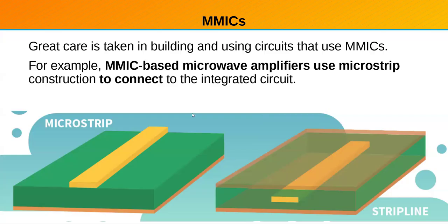And you kind of want to do that to control the impedance and also the length of them so that you don't get phase differences. Like if you're doing I and Q circuits where they have to be 90 degrees out of phase, you want to make sure that you don't get a phase shift between the two and get them out of the 90-degree phase difference. Otherwise, you can't generate or eliminate a sideband when you're doing that type of single sideband generation or detection. You don't see strip line that much.